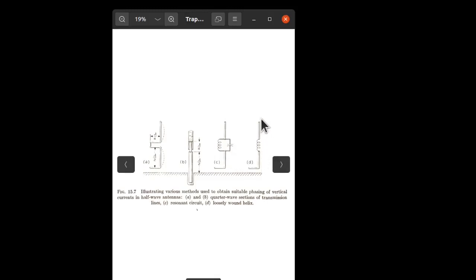Or we may separate the two elements by an inductor of sufficiently large reactance to separate the two, so that this acts independently of this, except through mutual inductance through the air. And this providing the additional length of this being too short in a different band. These are for multi-band or array constructions.